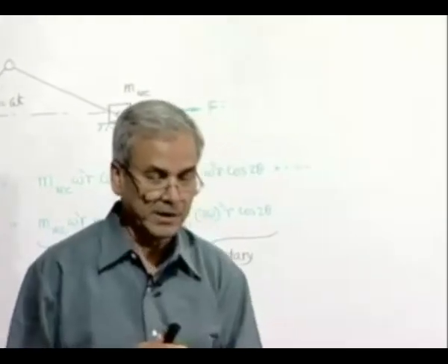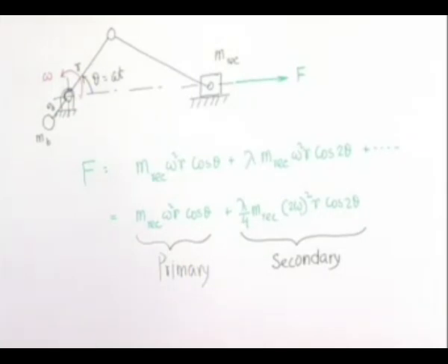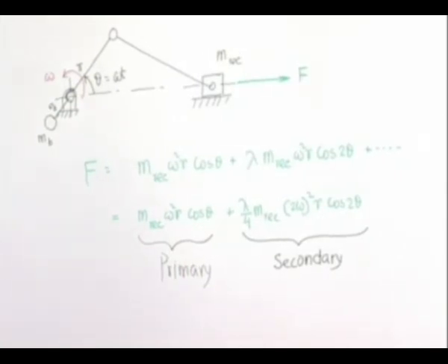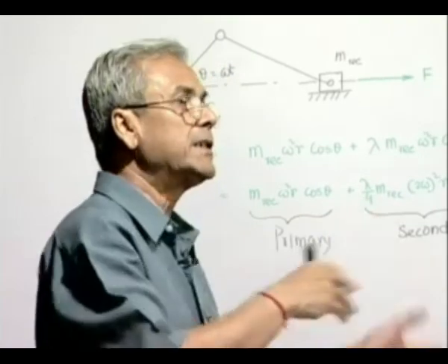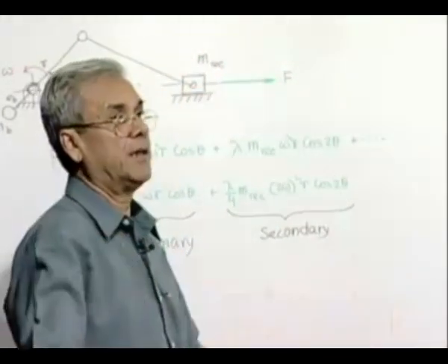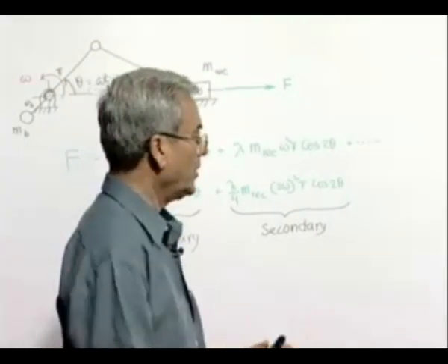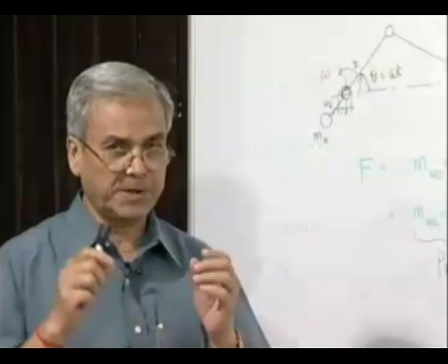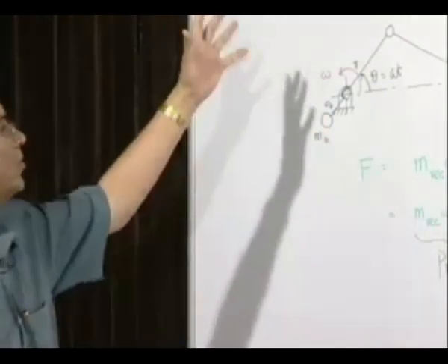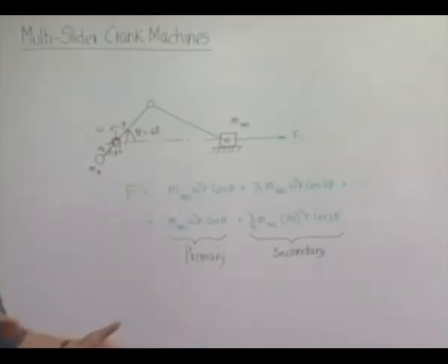So, in such cases, if we design the machine or the engine in such a manner that the unbalanced forces of individual cylinders or individual slider crank mechanisms neutralize each other, then it will be a very nice and convenient situation that the whole engine as a whole will be free from unbalanced forces. And now what we start discussing is precisely how to take care of the unbalanced forces in case of multi-cylinder systems or multi-cylinder engines by suitable design.